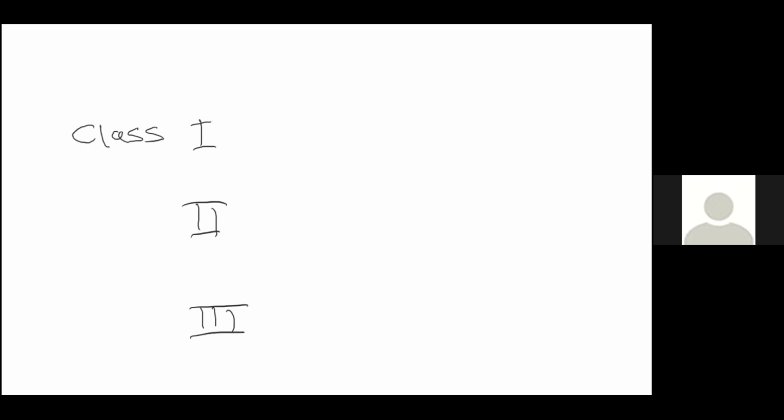Class 1 doesn't have a symbol, but it has an earth wire that is connected to any conducting parts that are accessible to the user. Thereby, if a fault occurs, then it will travel down the earth wire as opposed to through the user.